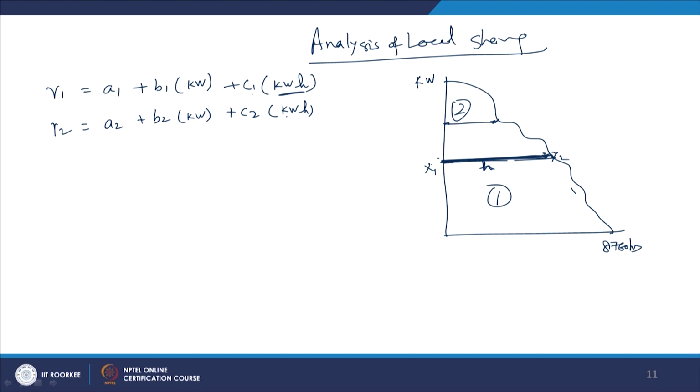right. Now, for operation practically, if you compare these two equations, the C1 has to be less than C2. Unit cost in base plant has to be less than the unit cost in the top plant or the peak load plant. So, C1 has to be less than C2. When C1 is set and B1 has to be greater than total cost.